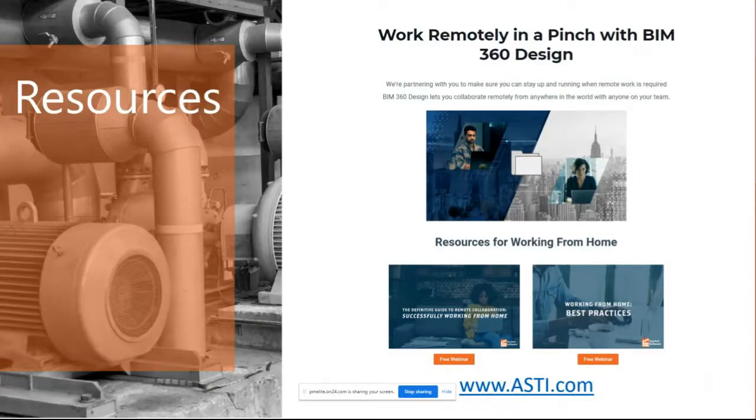All right. And another question is, would you prefer we use PDFs for a background or perform a PDF to CAD convert and use the CAD file for the background? The CAD file is probably going to give you more snap points than the PDF. It's just if you only got PDF, like some companies do, then you would use it and use that enable snaps. But I would use CAD.